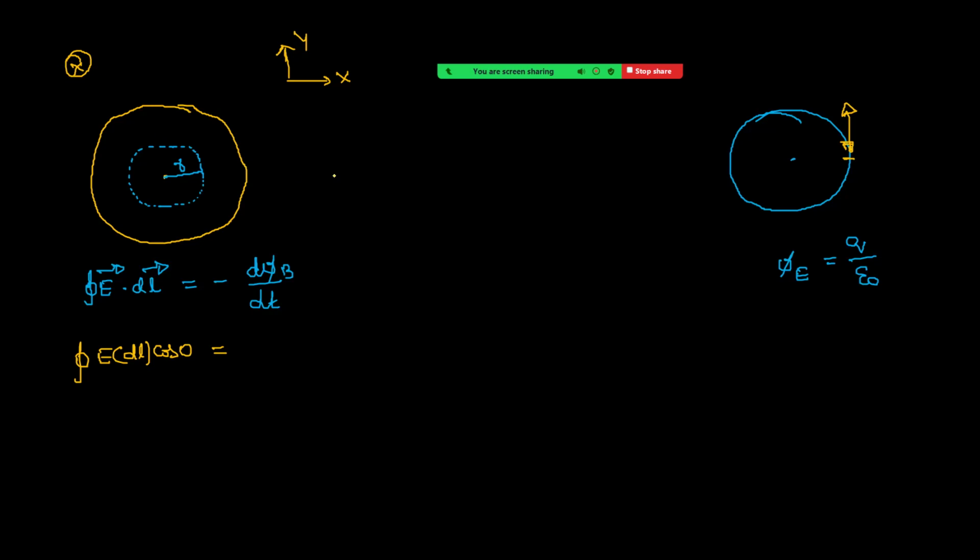Therefore, due to the induced current, the magnetic field must be outwards, that means towards us. So keep the thumb of the right hand towards us and curl the fingers. Now the curling fingers are anti-clockwise. That means the electric current is anti-clockwise.